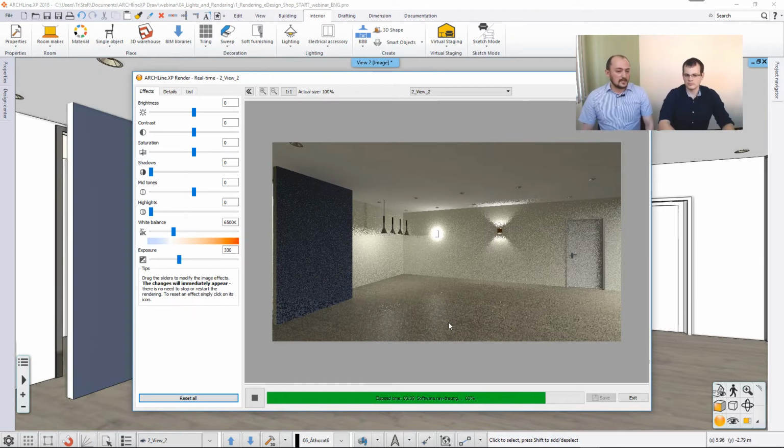Sometimes, and this could be a trick, you don't even have to add the same amount of light sources that you really have, because keep that in mind. When you have a light source, ray tracing will track that light source. If you have 2 light sources, ray tracing will track those 2 light sources, and then when you count up the light sources, the ray tracer will have to deal with more light sources, and that takes a longer rendering time. So if you would like to conserve rendering time, you would like to make it shorter, just as my colleague told, first things first, you will turn off all the light sources, all the lamps that are in other rooms, because you don't want to waste time calculating the zero.